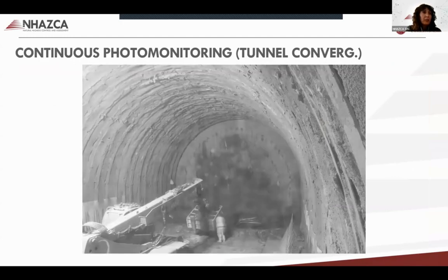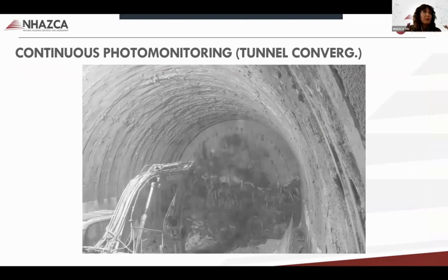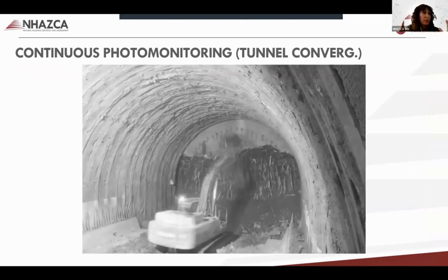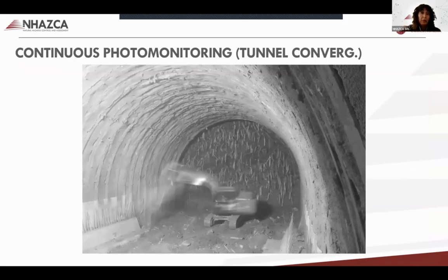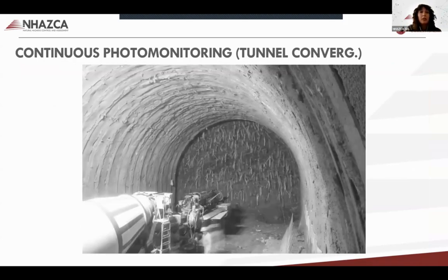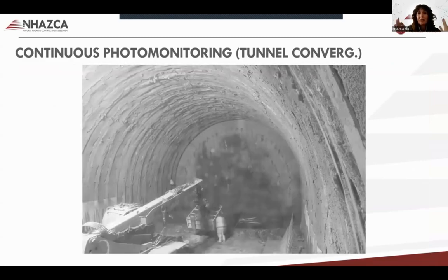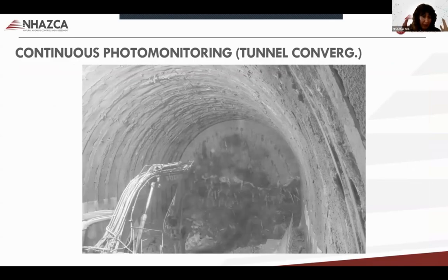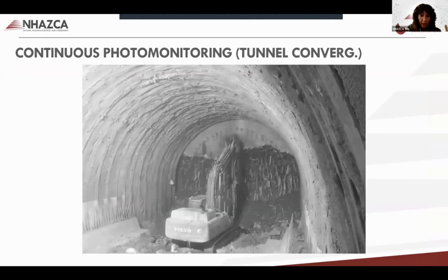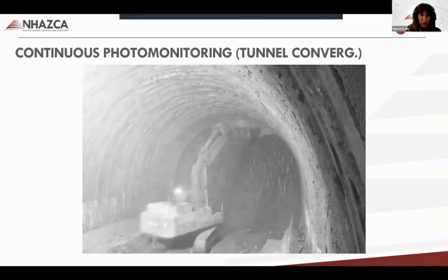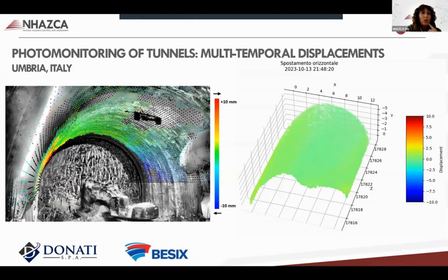And what we do during the excavation is monitor the tunnel convergence, which is normal during the excavation of the front. But of course, with this technique, we can assess if the tunnel convergence is in some range and threshold, which is safe, of course. So at every installation of the supporting arch, we do this monitoring.